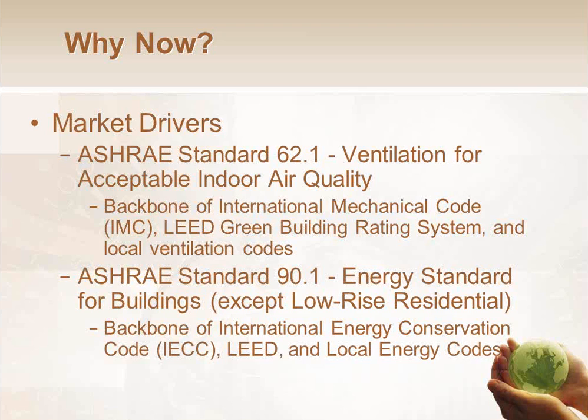And overall, those rates are higher than they used to be compared to the buildings that we're retrofitting. So that ventilation rate is about 50 to 75% higher than what it was when these buildings were built between World War II and, say, 1990. So the buildings you're retrofitting need more outside air now when you rehab them.